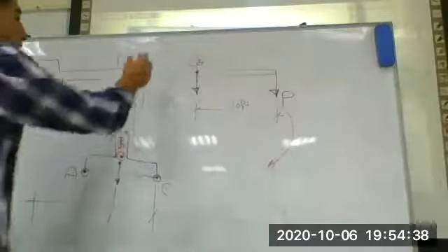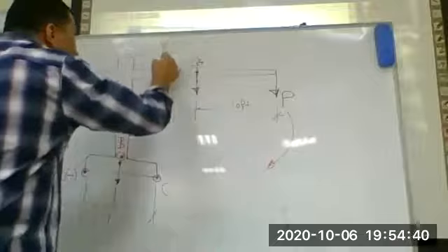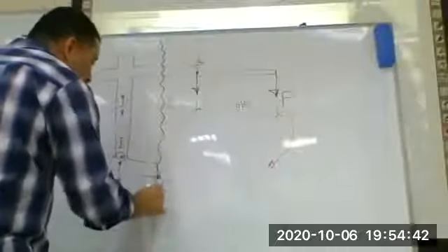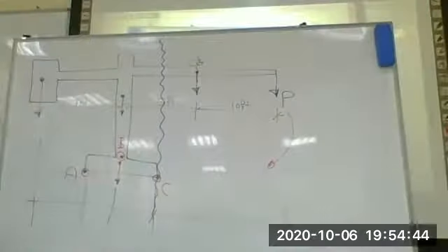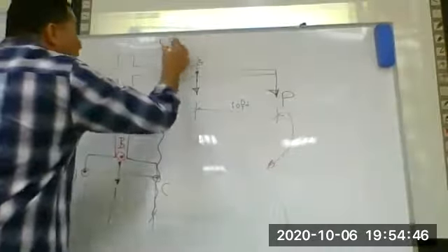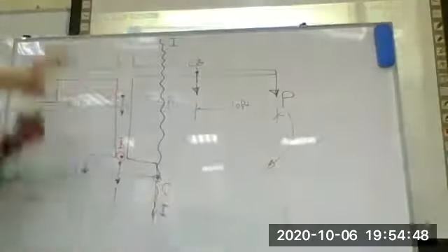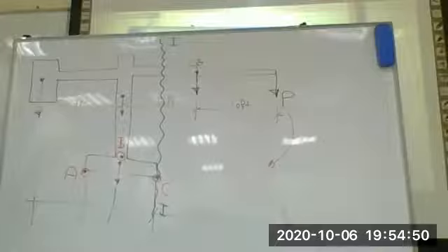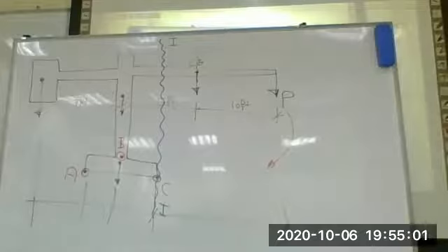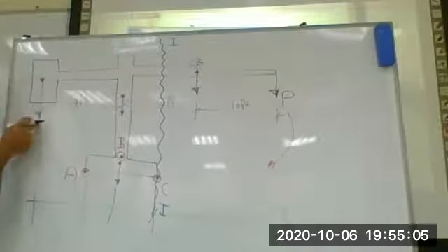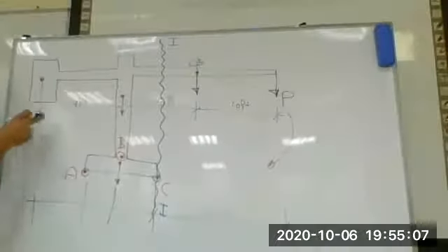For the equation, I will take a measuring line, we call it I. That means all the forces on this line in the right hand side give moment at this point, correct? And all the forces on the left hand side give moment at C as well, correct? It should be equal to 0. Okay, how many here? 7,000. The counterweight is 7,000 pounds.